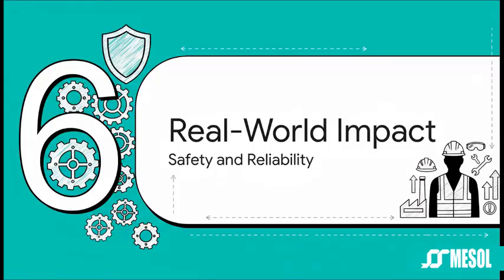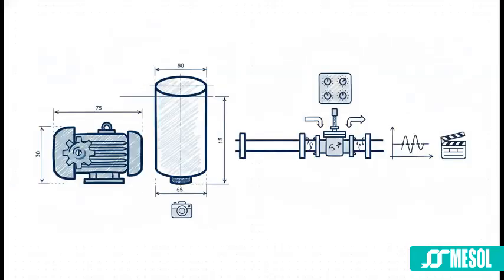All right, let's bring all this theory back down to what really matters on the plant floor: safety, reliability, and making sure our operators are ready to handle anything that gets thrown their way. So why does getting this modeling fidelity right actually matter? Well, think about it like this. For sizing a pump or a tank, standard equipment, a steady-state model is usually perfectly fine. But for sizing the control valve that actually operates that pump, you absolutely need a dynamic model. You have to understand how that valve is going to respond over time to changes in the process. It's a perfect example of needing the right tool for the specific job.